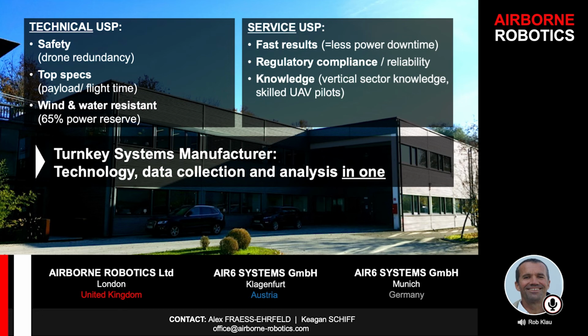You also get a reflectance level. If you scan a piece of roadway, you'll see most of it's black, but the white lines come up bright as can be. Often the Lidar scanners will pick up infrared as well. So then you can do analytics on vegetation with raw Lidar. Well, that is an infrared component that will come into it. So you typically get infrared, you get reflectance.